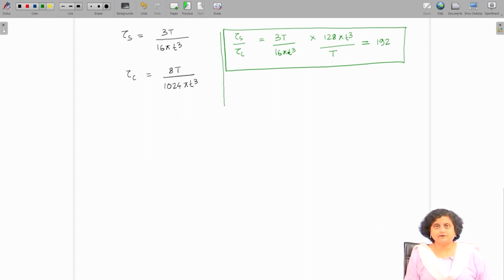But there are aircraft structures where it is not possible to have a closed cross section, and for certain other design requirements we will have to stick to an open cross section. So, whenever we face an open cross section, we should be more careful about how it behaves under torsional load, because the open cross section beam or shaft is more vulnerable to a torsional load as compared to a closed cross section. So, with this I will end this lecture.